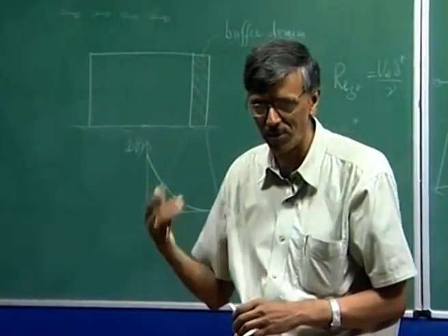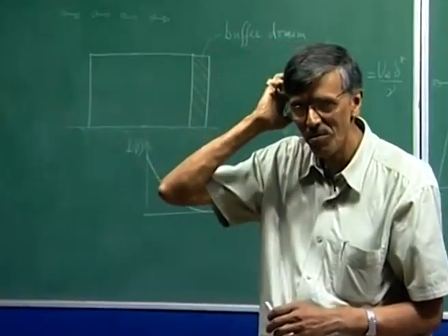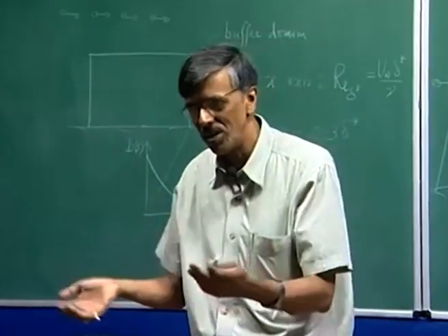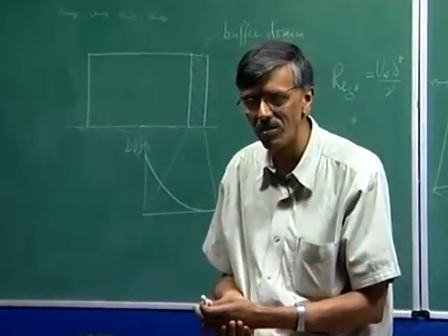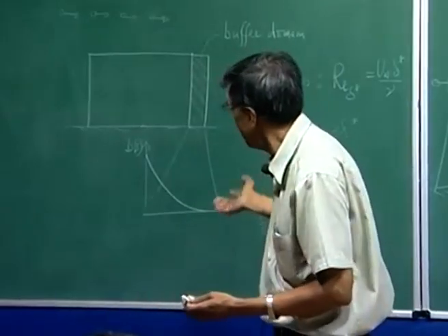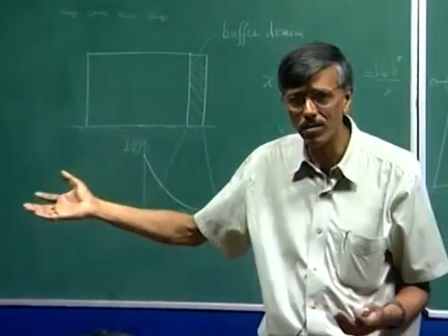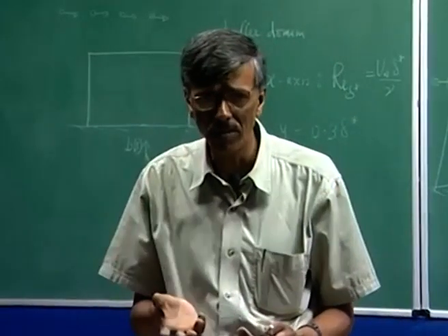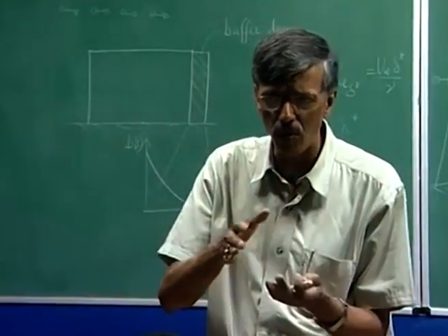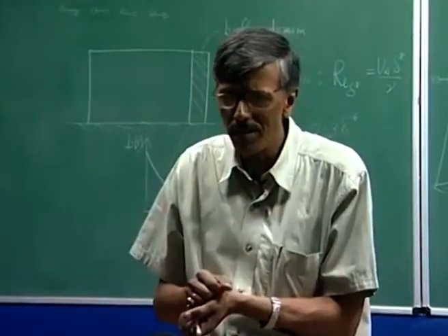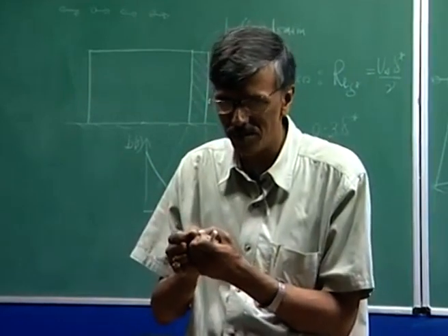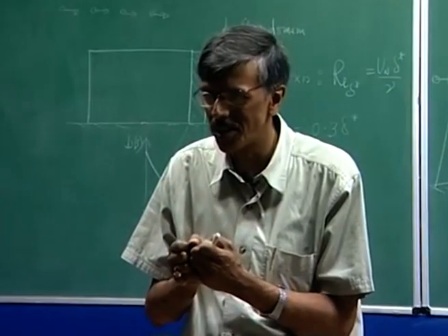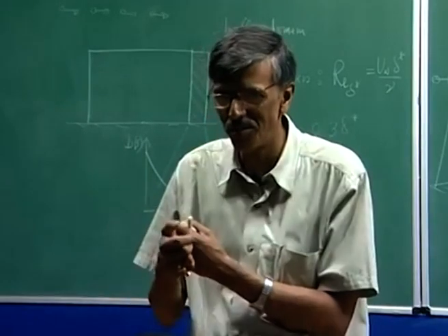That was the reason that we actually proposed this model, and we wanted to show the receptivity of the shear layer to some kind of periodically convecting vortices. You would see an identical scenario, and it is quite relevant if you are looking at an internal flow inside a turbo machine: the vortices will be shed from the rotor. They will be essentially viscous vortices. They will not go at c equal to u infinity.